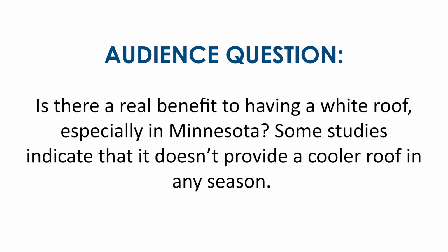The air temperature above a roof, there's wind, in particular if you're up a floor or two, and there are all sorts of discussions about how much of a heat gradient is going to be maintained right there. For these climates, it's not a big benefit. What it does help, and why it's a separate point for LEED and for other green building rating systems, is the heat island effect for the neighborhood. So for your individual building, you might actually consume a little more energy. But when we have acres of asphalt and dark roofs, the whole city starts to heat up a little bit. And if we can reflect that back, that has a heat island impact that is perhaps greater than the individual building impact.